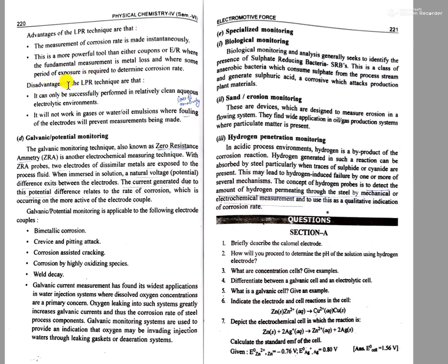And the disadvantage of this LPR technique is that it can only be successfully performed in relatively clean aqueous electrolytic environments, and it will not work in gases or oil water emulsions, or where fouling of the electrodes will prevent measurements being made.